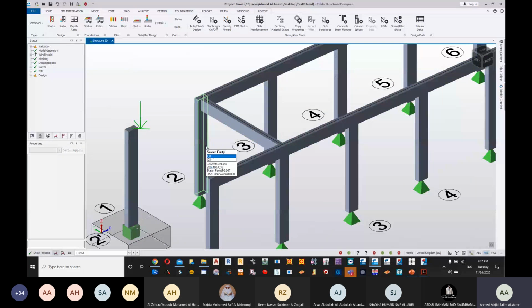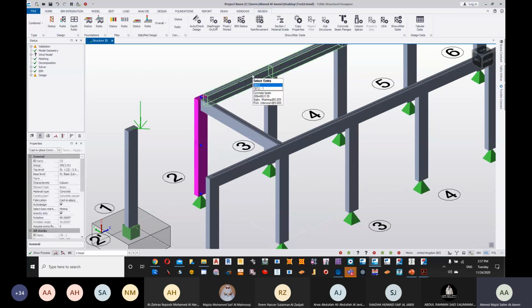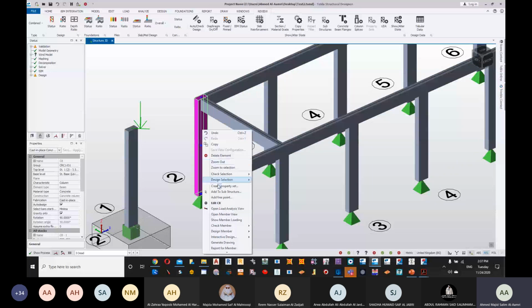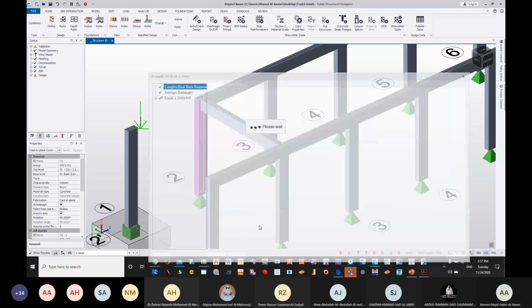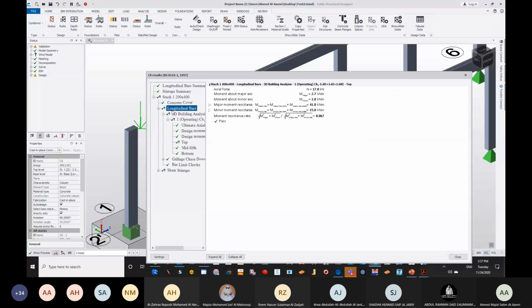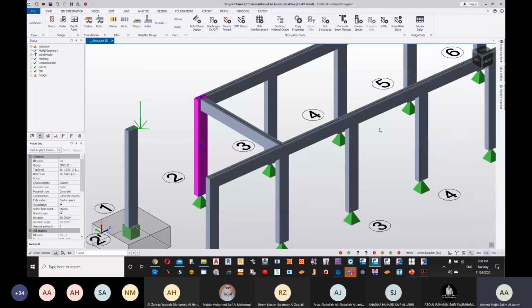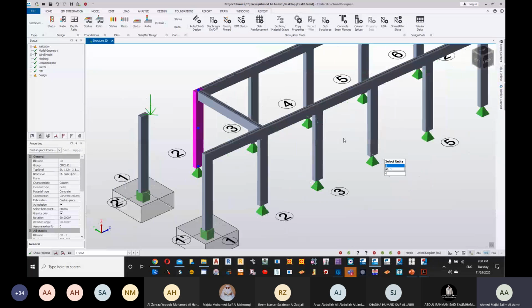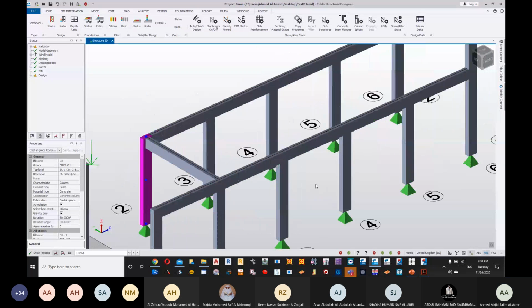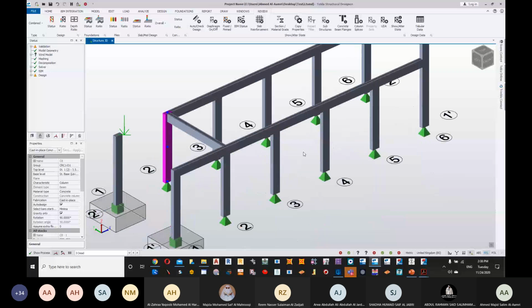Now if we go here, check this particular column, you can see there is a beam on one side, there is a beam on the other side as well. So in both sides we have the column having a restraint. So if we click now and check, you can see in the first direction we have it to be 3.1. In the other direction we have it at 3.1 as well. Are we clear how the length is changing from one direction to another direction? Is it clear? The matter of Lx and Ly?